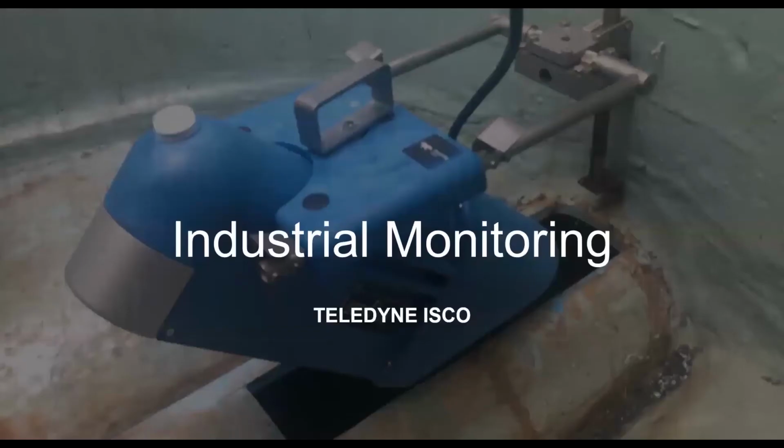So when we're doing industrial monitoring, we're seeing this kind of application more and more, which is ideal. If you can do this, this is perfect because now we're reading level right below roughly the handle, and we're reading the laser velocity right in that pipe. So now we have good hydraulic conditions. We don't have somebody that grouted in an invert that's maybe not perfectly symmetrical. So this gives you a much better accuracy condition.